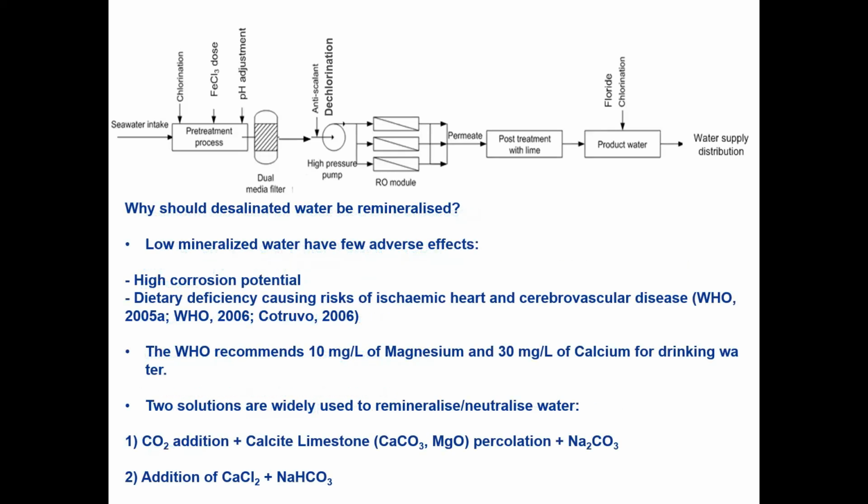And lime. Demineralized water has a few adverse impacts: corrosion potential, dietary deficiency, and risks of heart and other diseases. Some recommend 10 milligrams per liter of magnesium.